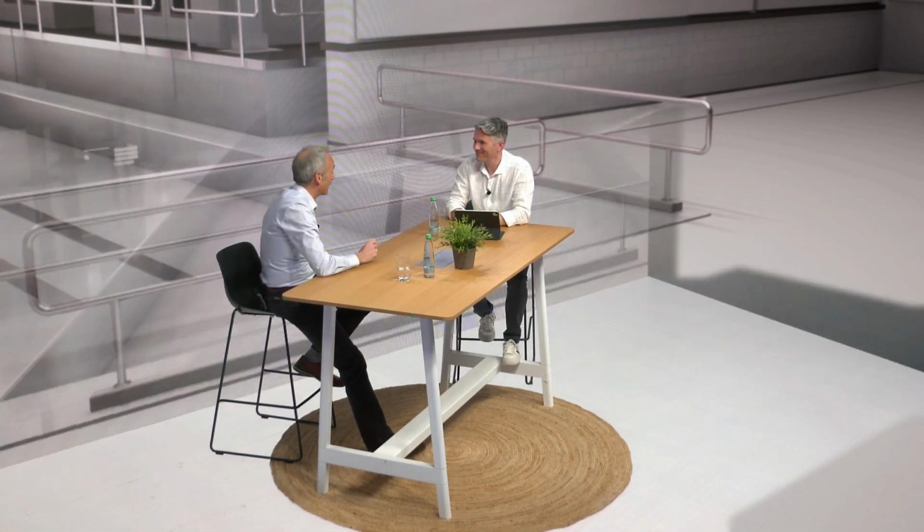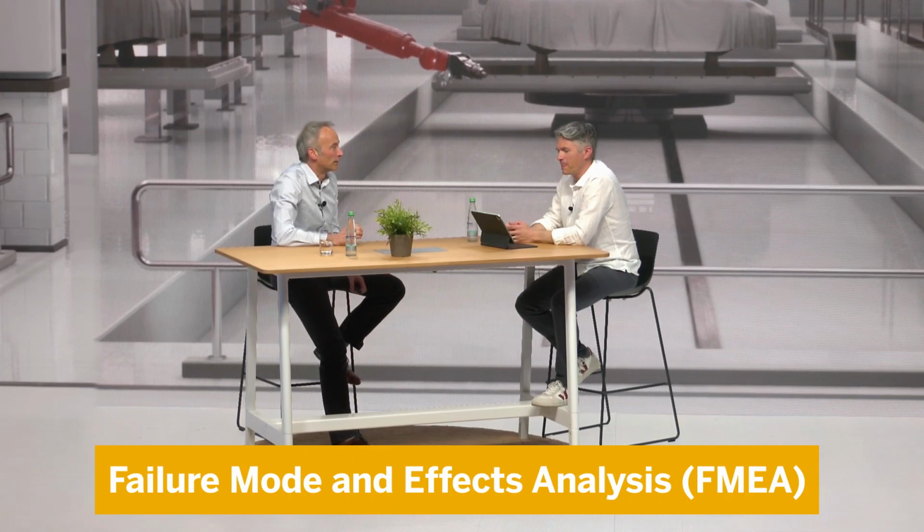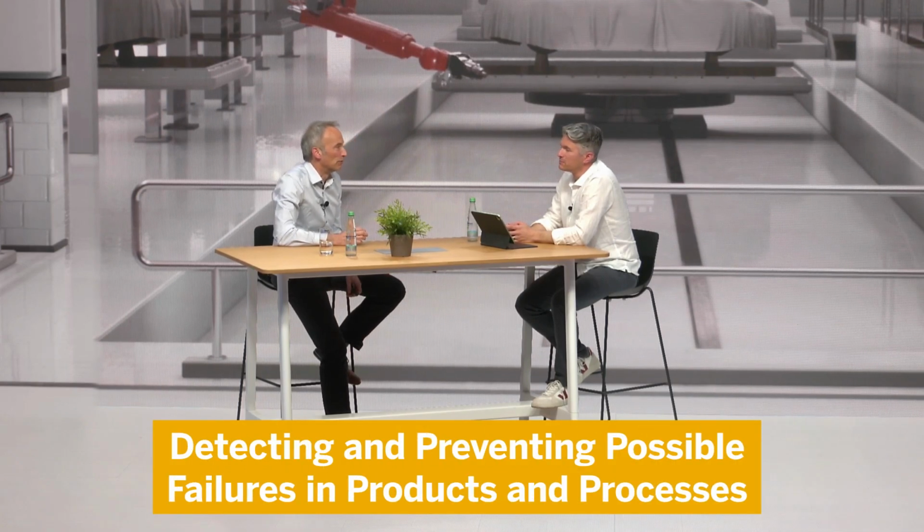Thank you, Yannick, for having me here. Difficult word or difficult abbreviation, but I will explain it to you. FMEA is a shortcut for failure mode and effects analysis. It's a method for detecting and preventing possible failures in products and procedures already in an early stage of the development, for example, in the design phase. So the purpose is to record failure modes and effects for a component or system.